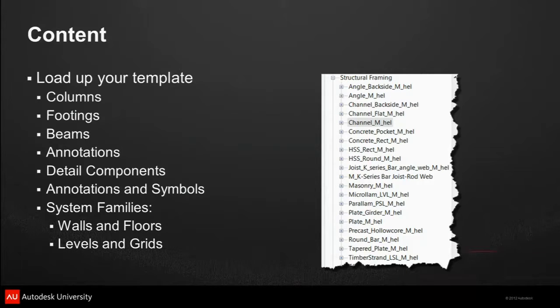System families. Go through and set up your walls, your floors, shear walls, wood walls, concrete walls, various thicknesses, floors. Once it's all set up, it's easy to duplicate to different thicknesses, but it's nice to have a placeholder value for everything in your model, in your template.